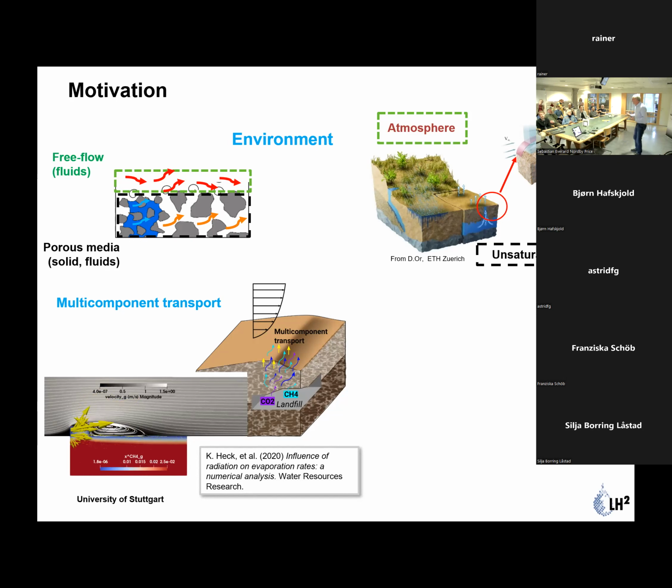And you cannot handle this with the Fickian law. Why? Very simple. You have a multi-component system. You need Maxwell-Stefan equation and so on. It's a really tricky thing to handle this. And of course, that's related to my question where I got an excellent answer from him yesterday, that it's not only temperature-driven and pressure-driven, that is density-driven and viscosity-driven too. Why? With this change of the components, you have a strong influence on density and viscosity.